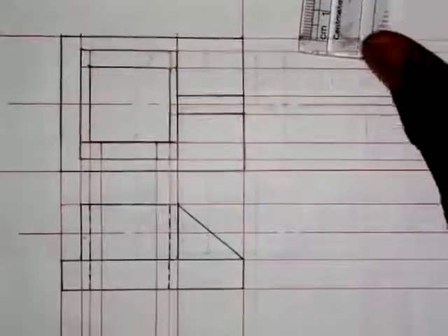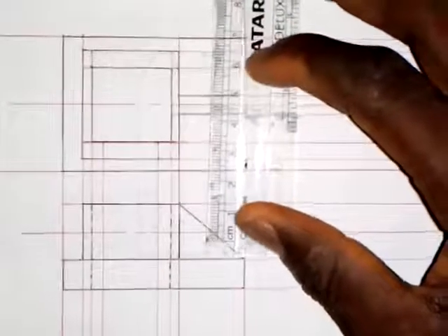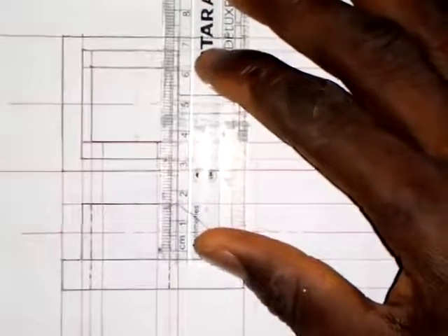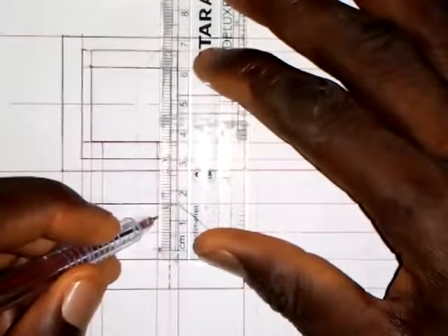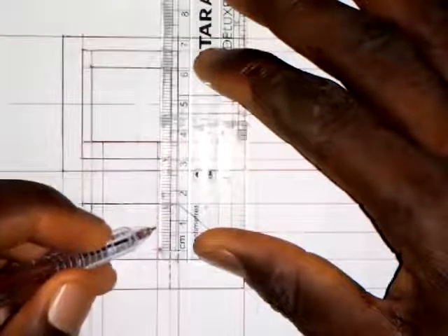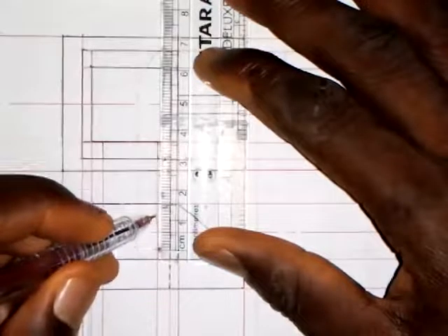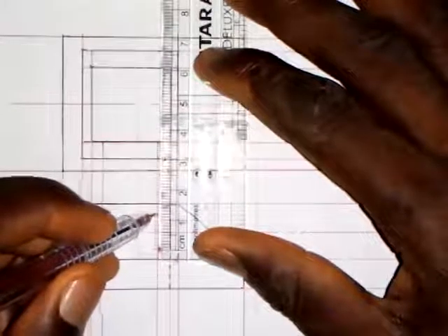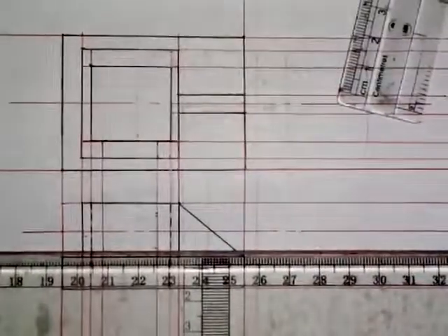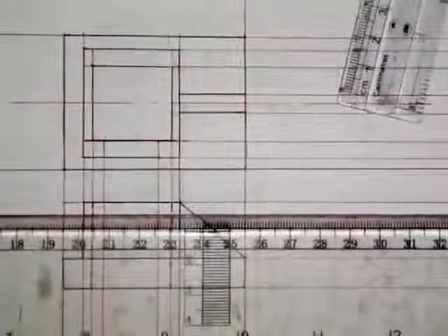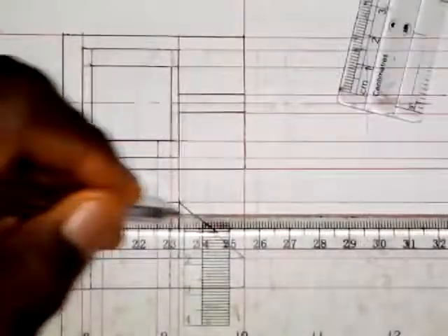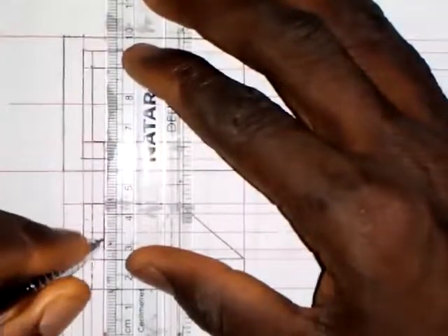Okay, so that's the horizontal center line, and the width of the rectangle is 12 millimeters. So that is 6 millimeters. From here I'll take 6 millimeters down and 6 millimeters up like this. So this is 6, making 12. So I will draw a horizontal line like this, and then it goes like this. So a horizontal line and this, and it goes like this. So I'm going to take in the rectangle.